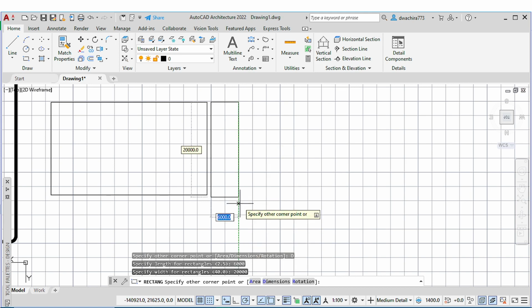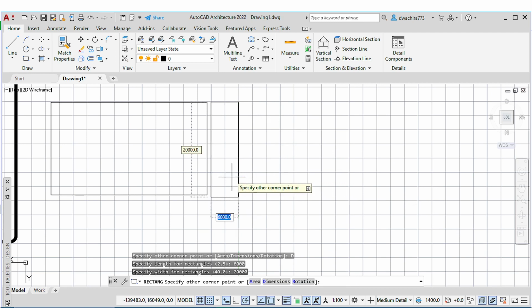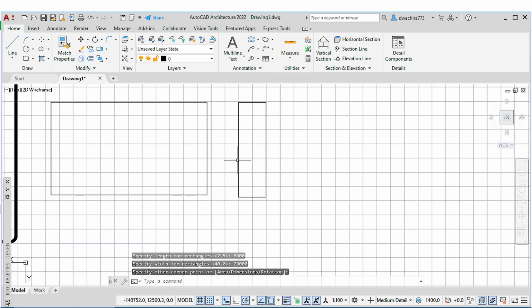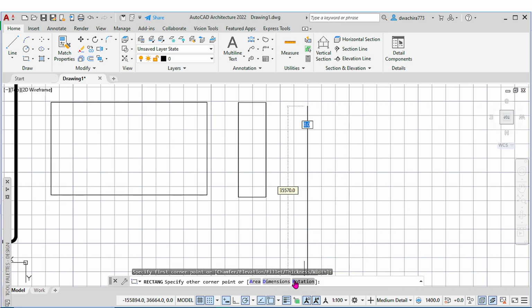You can note that they have been added from that point or from this point using the dimensions. Now you just need to click to specify the direction. For example, I want it to be this particular direction. So that is it. Once we have said, the option to add the area dimensions only appear after you click to start placing. You can note they will appear here.